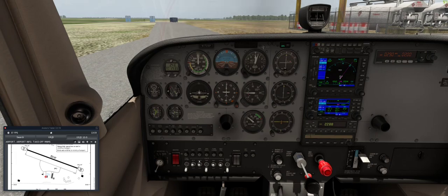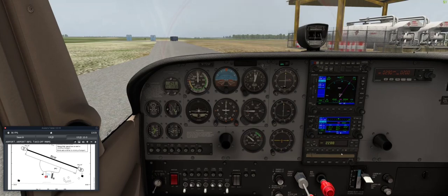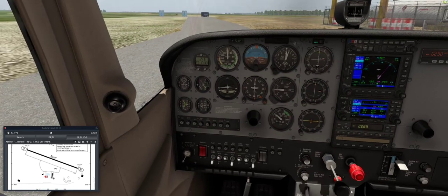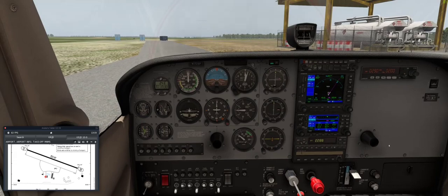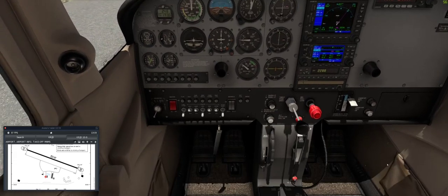You don't need the fuel pump switch on in the fuel injected version, which the 172S is. I think the checklist has you turn it on and then turn it off. I think that primes the fuel injection. Maybe it matters, maybe it doesn't. For practical purposes, it doesn't seem to matter.